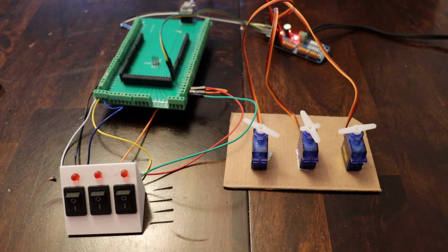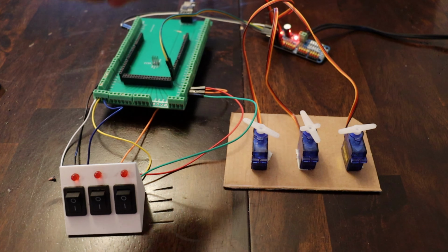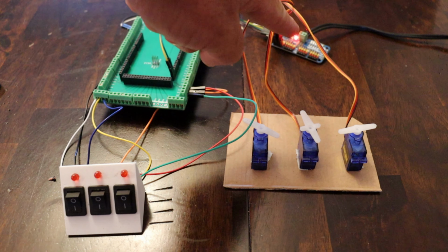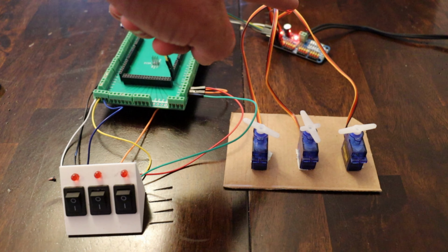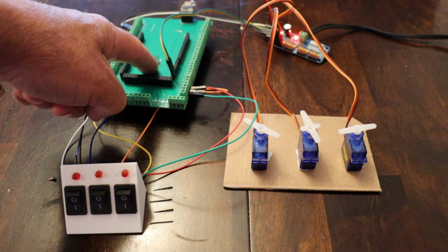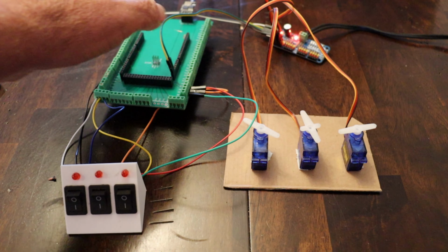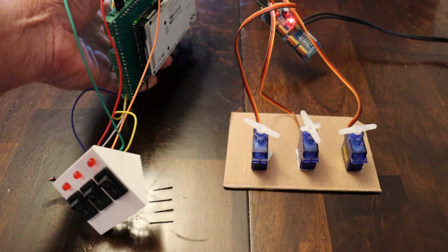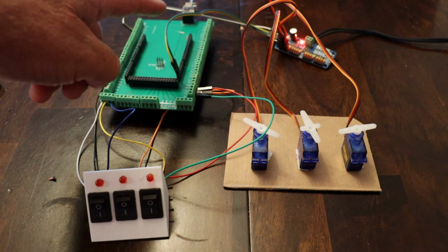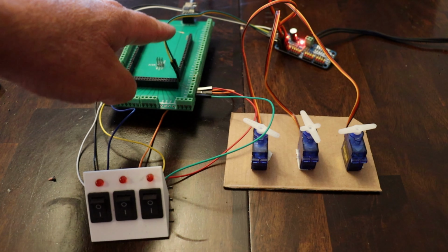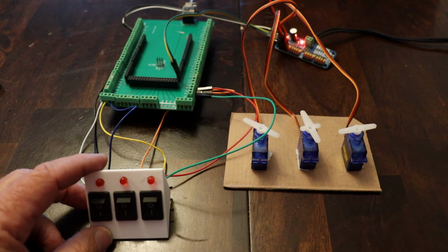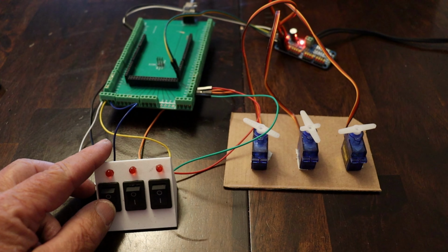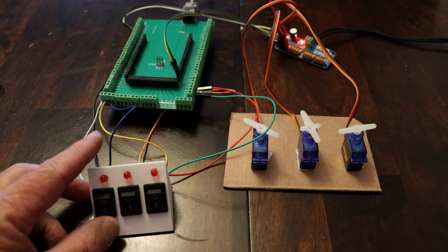All right, we're ready to show how it works with our latching switches. So we've got our 3 servos connected to our PCA9685, kind of in the back there. There's a power cord going to the wall with a 5 volt power supply connected to drive the servos. Underneath here is my Arduino Mega. So I've got my I2C connector going to the PCA9685, and here are my switches, my toggle switches, or rocker switches in this case, with the LEDs.